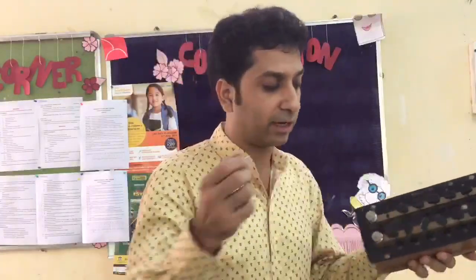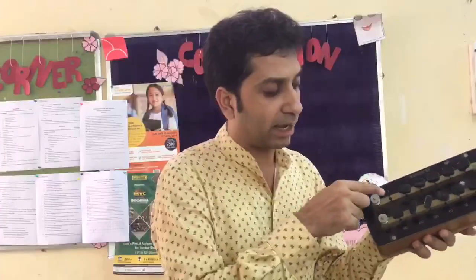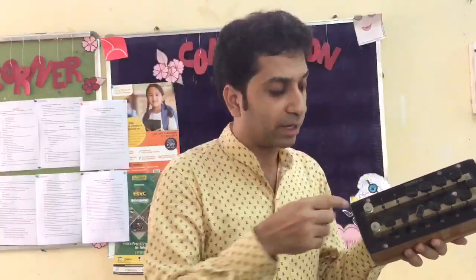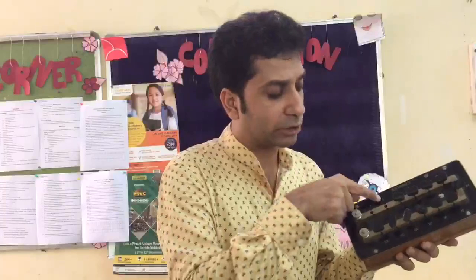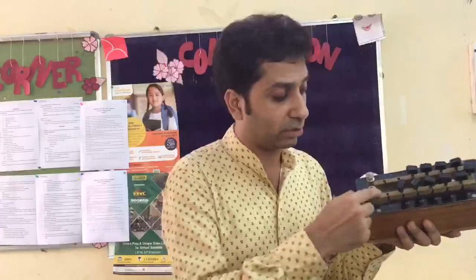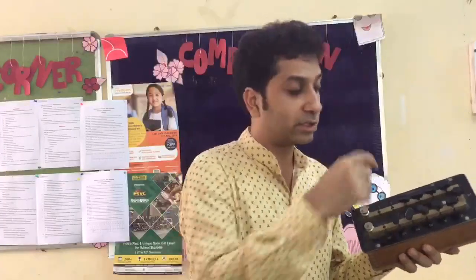If you want to introduce a known value of resistance in the circuit, go for a resistance box, because in this the values are displayed. If I take out this key, it means I have introduced a resistance of 1 ohm in the circuit. And if I take out two keys, internally they are connected in series, so 1 plus 2 is 3 ohm. Or if you want a higher resistance, you can take out 500 plus 2 plus 1 to get 503 ohm. So this is the way to introduce a known value of resistance in the circuit. This is called a resistance box.